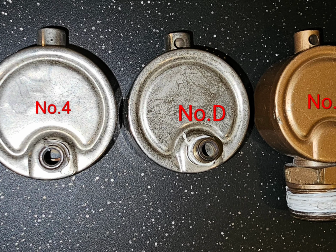Why? Just the fact that it's a cast iron radiator, they hold the heat better, and it allows steam to flow through it easier without losing temperature the same way. However, under no circumstances should this air vent be used on a steel convector. Why? I'm going to tell you why. I did videos on steel convectors years ago. They're still up. You can go ahead and take a look at them. Steel convectors do not hold the heat the same way. Steel convectors will cool down significantly faster.